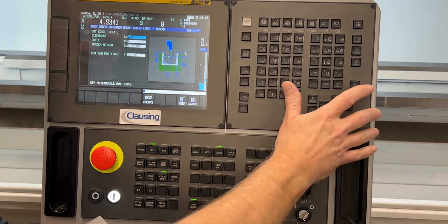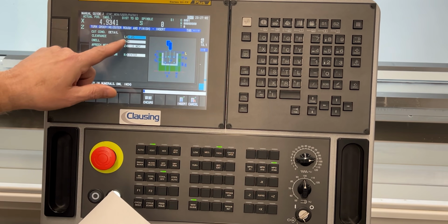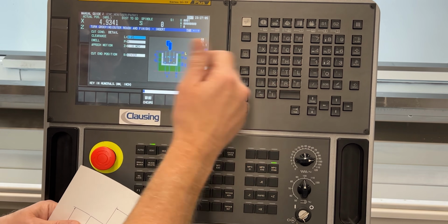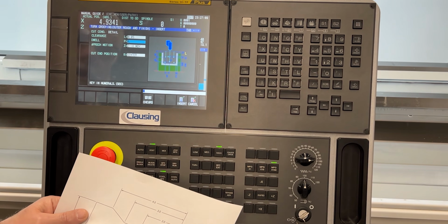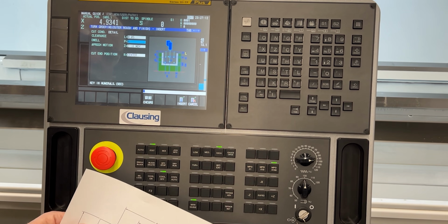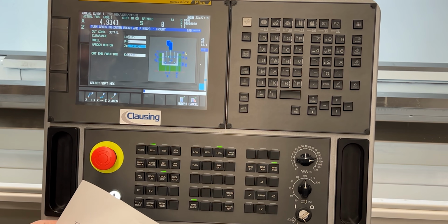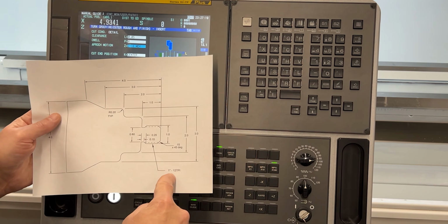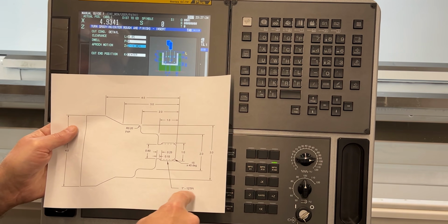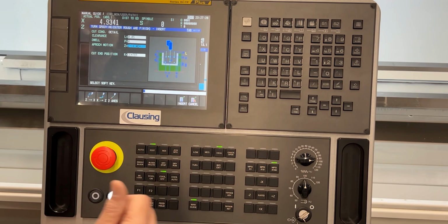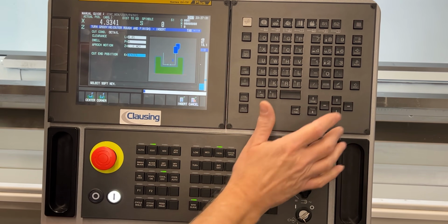The next part of this roughing information is our clearance. When we approach the part, it'll remain away by 50 thousandths. And then how much dwell we have at the bottom, once we get down there, I'm going to leave that at 0. And then the approach: when I came back from tool change, I stopped out here, so it's going to do a Z first, then X to get to the start point of the groove. So we'll leave that there. We have different selections that we can choose from.